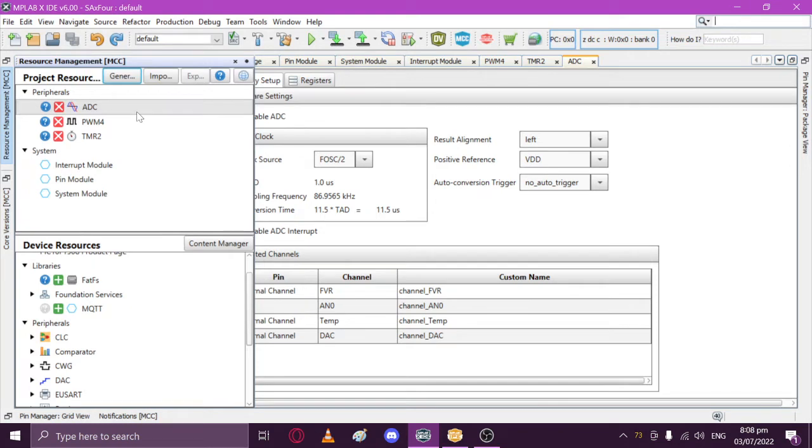Okay, so it is time for me to explain this project. So this project aims to have a potentiometer serve as a joystick to control the steering of a remote controlled toy car, with the steering direction of the wheels of the toy car being controlled by the servo motor. So this potentiometer will input an analog signal to the PIC, which then sends a signal to the servo motor on the toy car to determine which direction it should steer to.